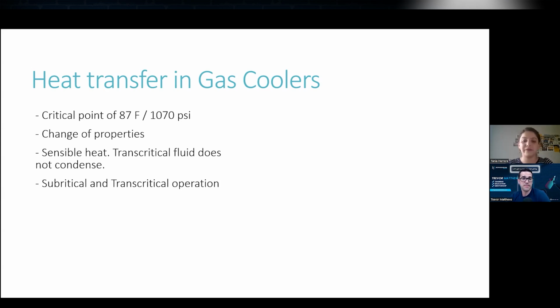That's correct. Okay. And for instance, that's the reason why some of our customers tell us, please give me a gas cooler, but maximum pressure drop of 10 psi, or really maximum 15 psi, because they already know that when they are working under subcritical, the pressure drop will be higher, and the one, as mentioned before, the one that will pay for it will be the compressor, but it will be the customer's pocket, right? Yep. Because it means more electricity consumption.